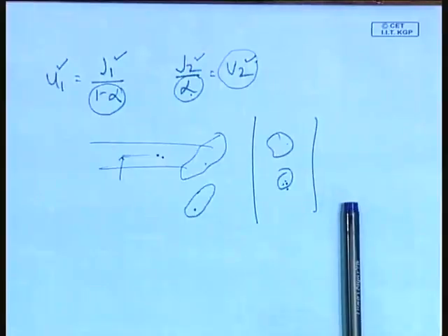It depends upon the difference in the refractive index, or it depends upon the difference in the attenuation of the two phases. In fact, I will tell you one thing. What we had done in our lab was, for air water it was not a problem. After air water we started liquid systems, flow systems. We started with water kerosene system. What we found, see, radiation absorption staying here, it is not possible, we will never get the permission. We were using impedance probes of different designs for different air water systems. We went on devising designs and we tried to use them for circular pipes, no problem.